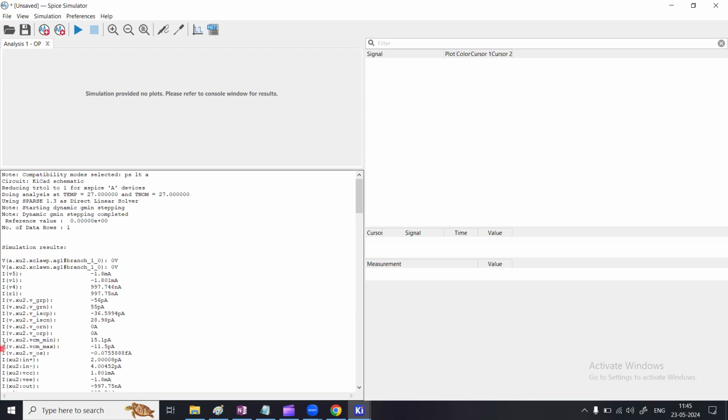These are all the currents being drawn by the components inside the sub-circuit. And remember, our sub-circuit is the OPA1641. So there are all the internal components inside this sub-circuit: the dependent sources, capacitors, resistors, diodes. Everything is there inside the OPA1641, which has been modeled by the experts from the manufacturer company, and they have given these. So these are the current values from those components.